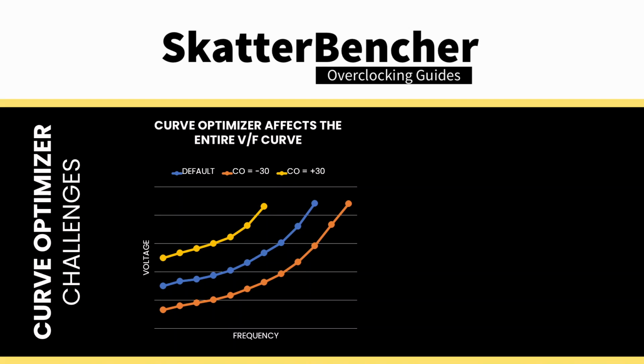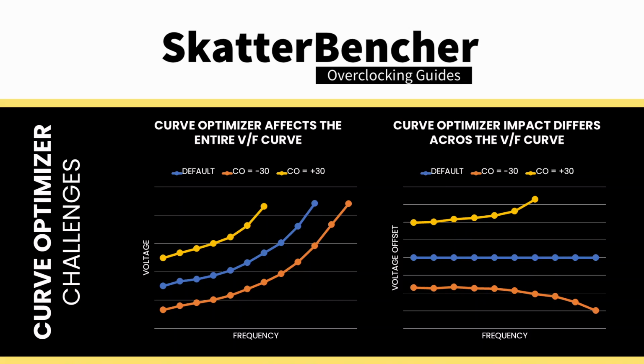Curve Optimizer impacts the entire voltage frequency curve, so it affects stability across the entire range of operating frequencies, from 600 to 6000 MHz. The same Curve Optimizer value impacts differently across the curve. If you're lucky, your CPU's undervolt margin matches how Curve Optimizer offsets the voltage across the curve. Then you'll maximize the performance gains. But if you're unlucky and one part of your CPU's VF curve has a lot less margin, then your Curve Optimizer tuning journey will be a rough ride.